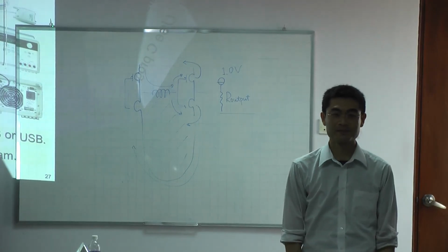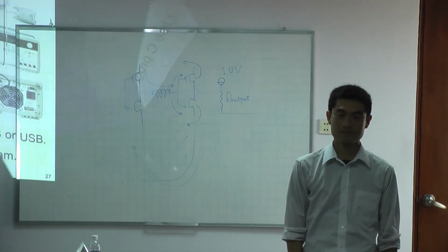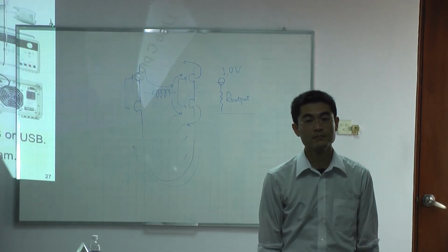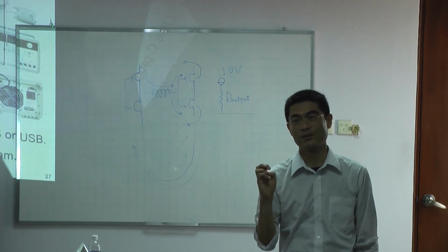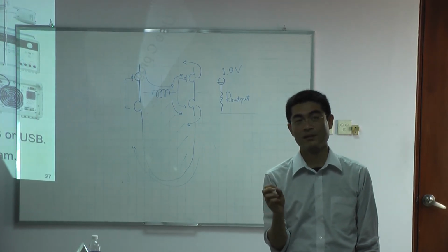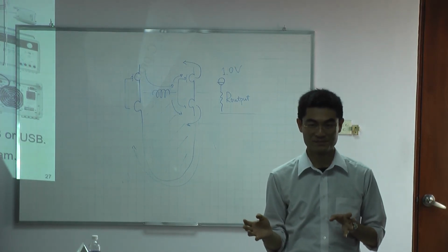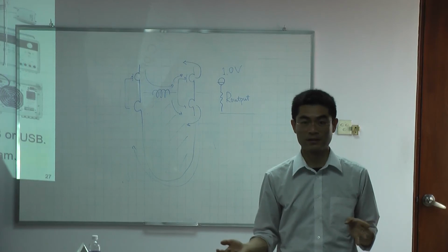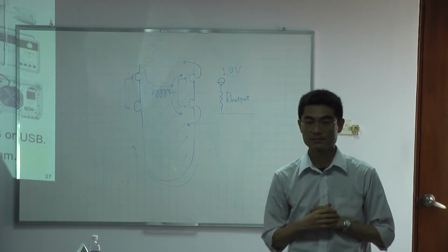Any other questions? So regarding the return path of the current, you have something measurable. But how can we simulate or analyze it in EDA? In EDA, we often have a ground symbol. So if we only want to measure the return path, maybe you will extract S-parameters from the layout. So you have signal lines and ground lines, and extract S-parameters from the layout by using ADS.